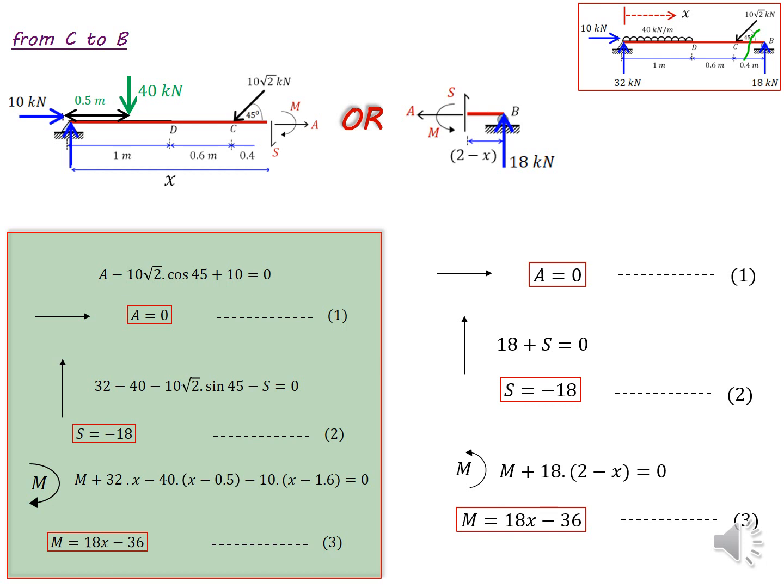Similarly, the bending moment, hogging moment is positive, and shear force clockwise positive. So if you apply the sign convention correctly on the left hand side or right hand side, and if you measure the lengths correctly to both sides, you will get the same answer. So it's completely up to you to decide which part of the beam you are considering to draw the free body diagram.